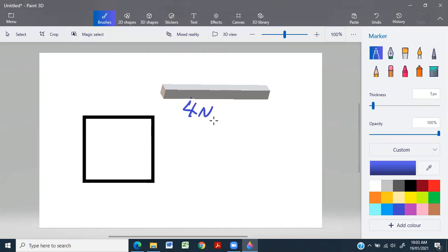So we want a way to find out how much it stresses the bar itself, because 4 Newtons is 4 Newtons. And if we apply that to a big bar or a smaller bar, the forces are more stressful for maybe a smaller bar than this bigger bar. So that's why we divide it by area, right? So it's force, or force divided by area.